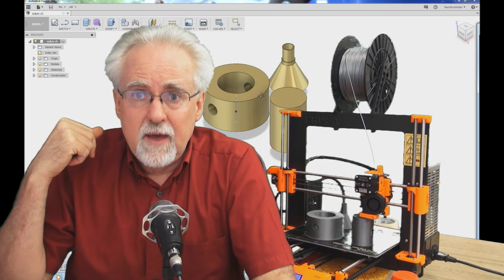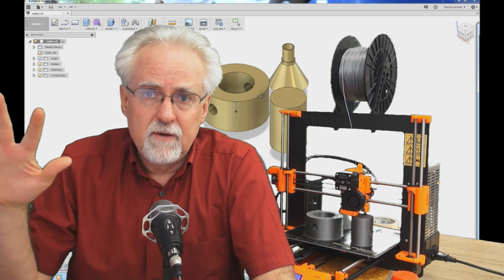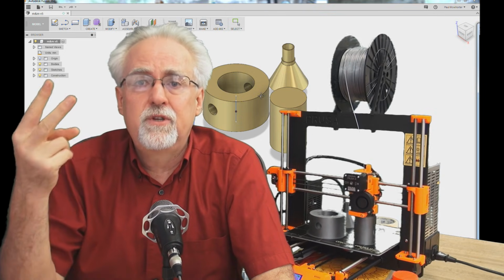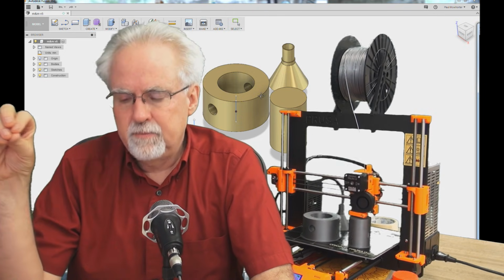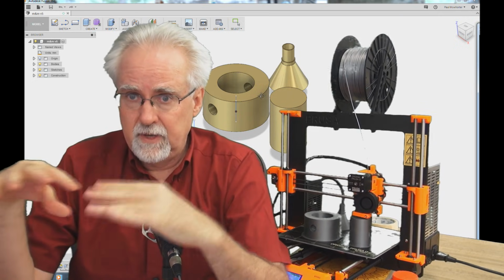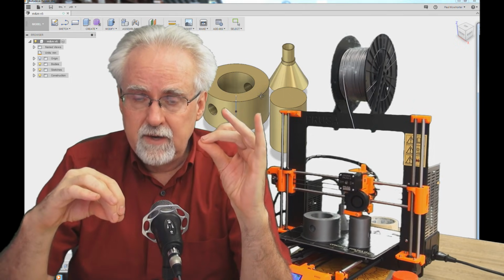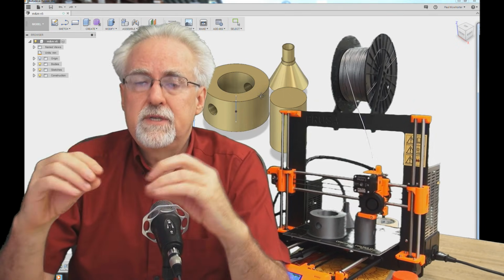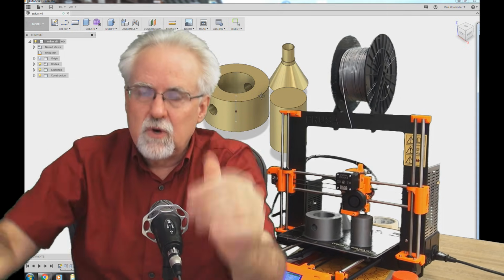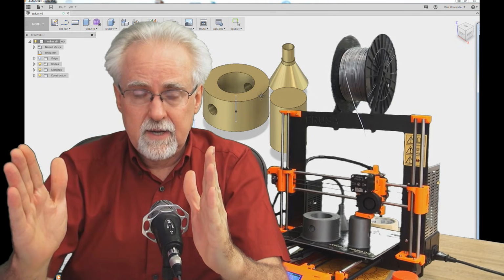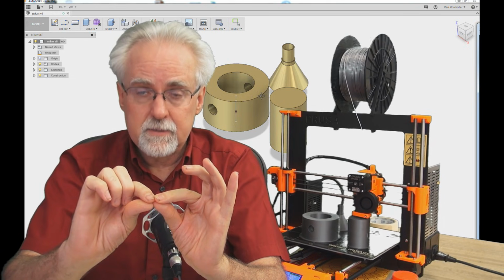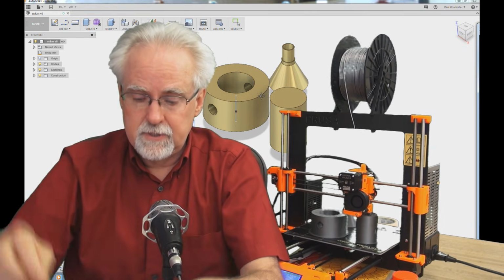The third reason that we struggle with Fusion 360 and we give up and go somewhere else is that we're not precise in our sketching with 2 things: dimension and position. Just like I say, you're mindful of the palette, tell it what you're going to do and then do it. Same thing, when you create an object, set the dimensions and set the position mindfully, deliberately. Don't just go out there and drag and draw a box. If you're going to create a rectangle, say, okay, it's going to start at a certain position that I'm going to specifically specify with numbers, and then it's going to be a specific dimension.